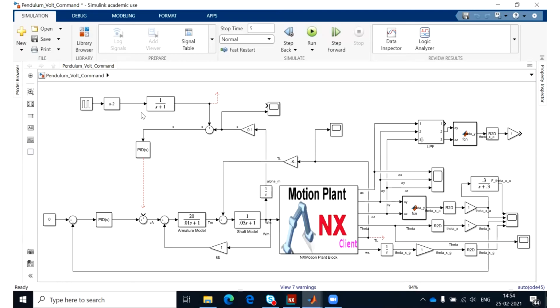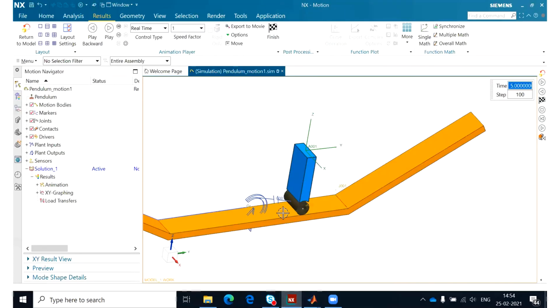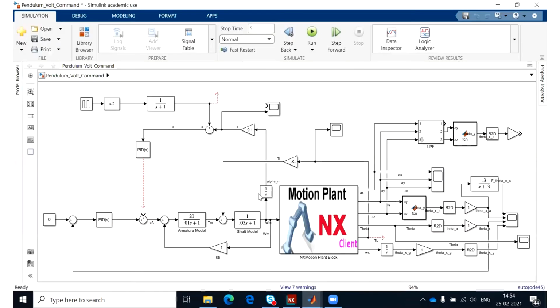And secondly, if you have a desired position, so let's say what you need is to send the pendulum 1 meter to the left and then wait there for a couple of seconds, and then 1 meter to the right and wait there for another couple of seconds, you can easily do that by applying a proper desired signal or a reference here to the second control loop.